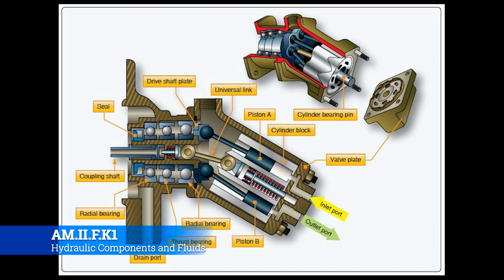It basically is the same kind of configuration with the pistons and the housing. The difference is that it's offset at an angle to make it fit in a certain area. What's really going to be fundamentally different from this one, though, is that the drive and the inlet and outlet port are opposed from one another. Whereas before you would meet up with a drive on one side, and often your inlet and outlet ports would be part of that. So you would just simply attach the hydraulic pump to the housing.